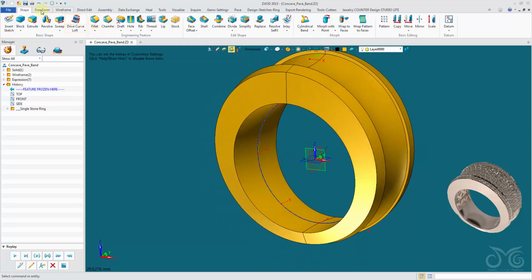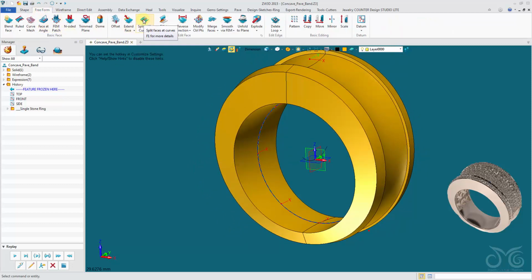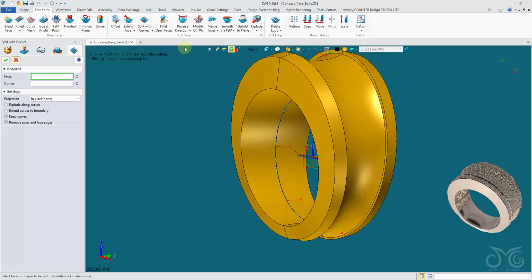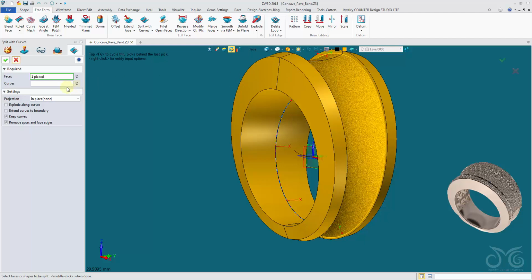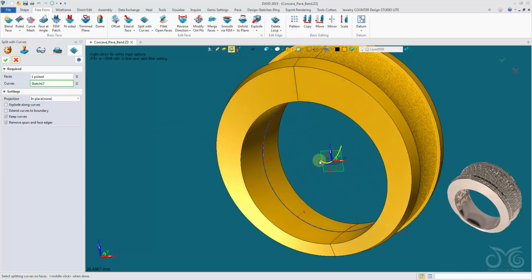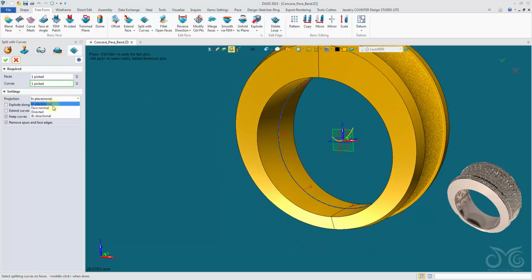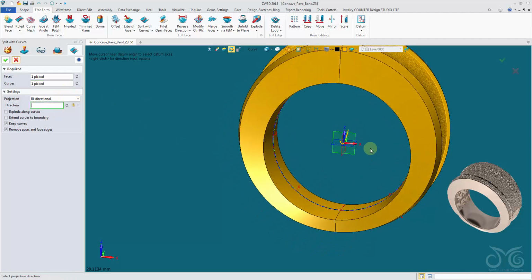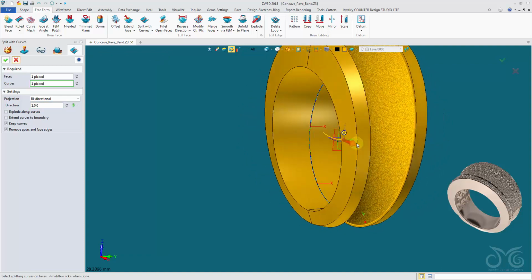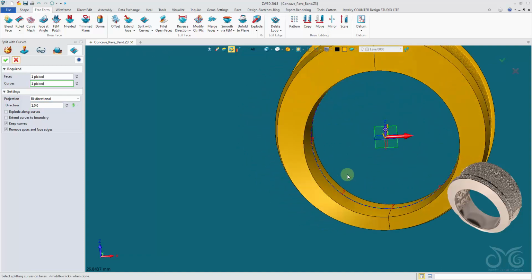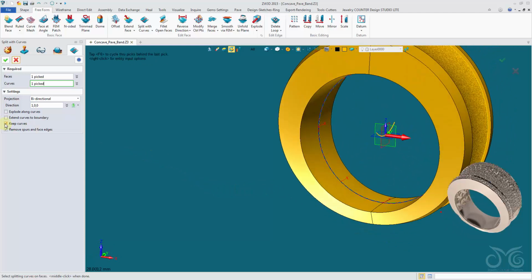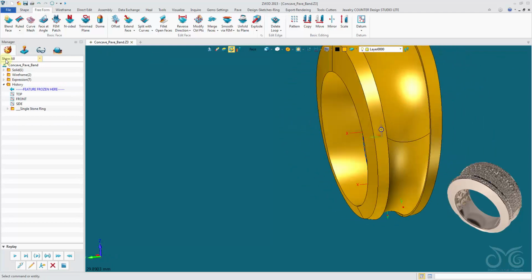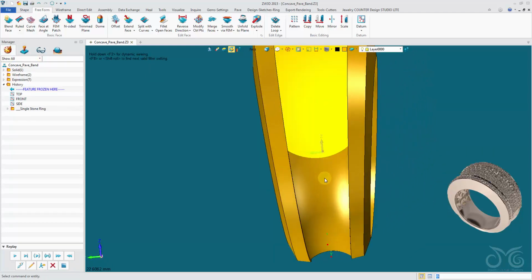I'm now going to use a projection and a split. Okay, we will split with curves this face. Remember, pick it as a face, not as a shape. The curves is our sketch. And we want a bidirectional projection along the x-axis. Okay, so it will be projected onto the surface and then we'll split along that surface. Okay, I do not want to keep the curves. Confirm the operation. 1 split, 2 splits. Okay, so we have 2 faces.